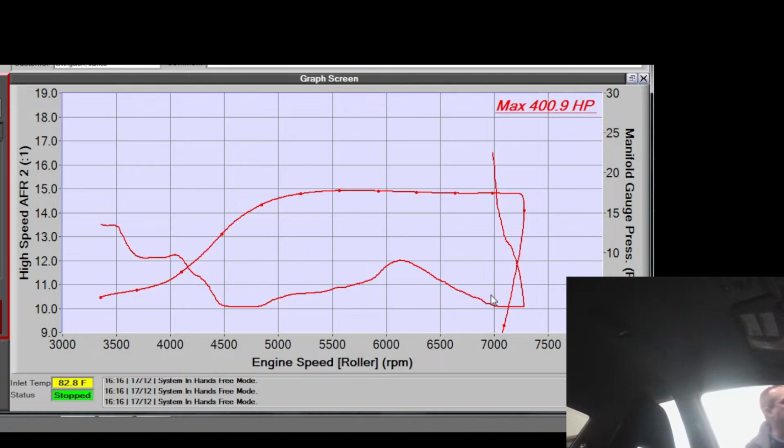Correct. They do not. That's why they don't work. That's the problem, because the fuel pressure goes up with boost and pushes the thing open. So the boost pressure is supposed to equalize the top of the damper, so that it dampens the same as boost increases, as fuel pressure increases. It keeps the disc in the center of the stroke, so it provides damping action instead of getting pushed to the end.